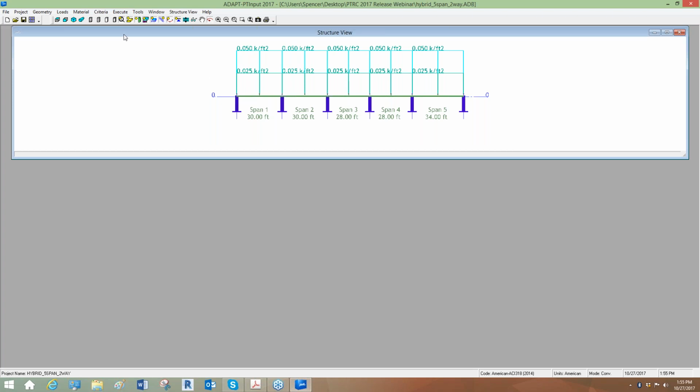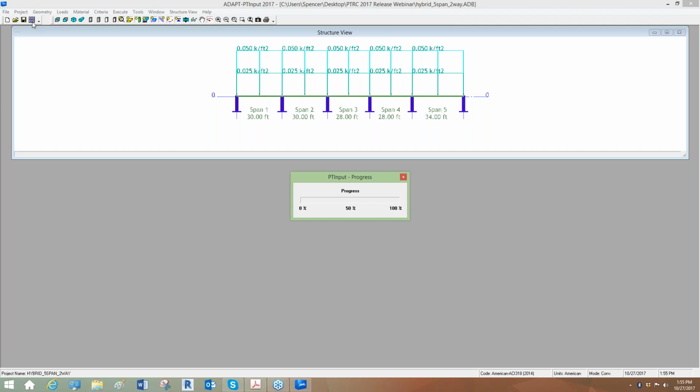Those curtailment rules are reflected in the Builder Summary sheet when you output the rebar, both in Builder Summary and also in block 10, the reinforcement output. And there are ways to actually make changes to reinforcement when you're in Builder Summary. I'll show that here in a moment.